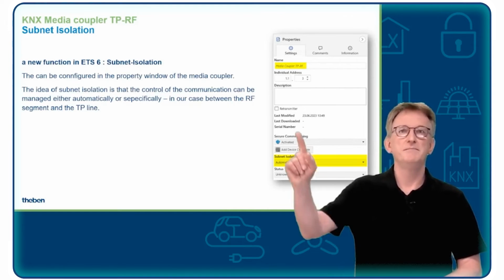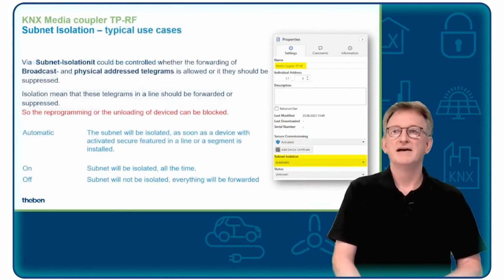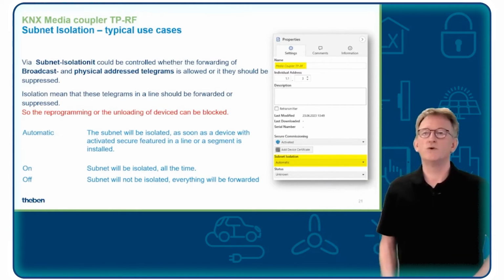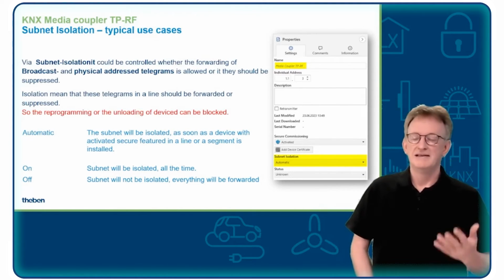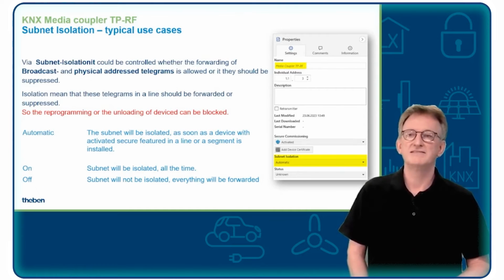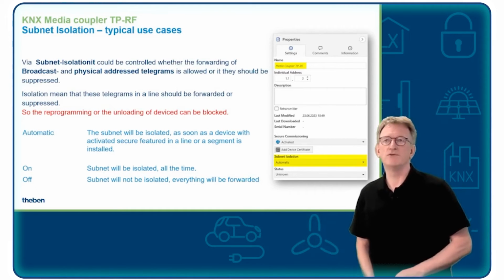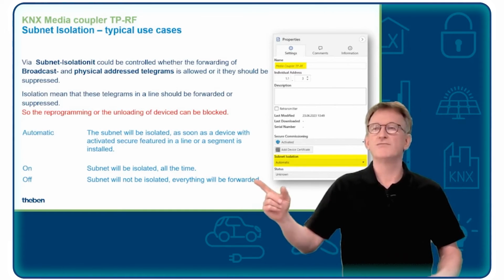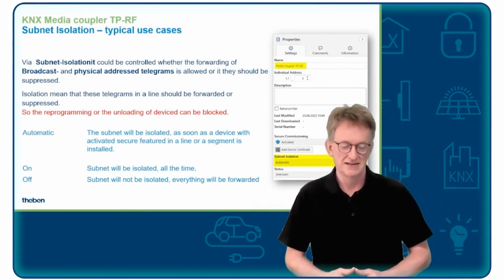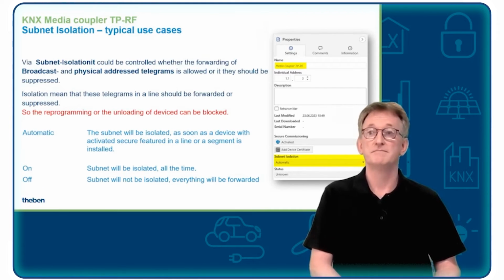You are doing that in the media coupler, as you can see here. Just go to subnet automation and say, yes, you have here 3 options. One option is automatic, so ETS will decide on its own. If there is a secure device, then it will run in secure. But you can also say it on, then it's always isolated, or off, it's not isolated, everything will be forwarded. And this is especially important for all broadcast or physical addressed telegrams. Also helps you to make your KNX environment, especially if you have RF environments, more secure.